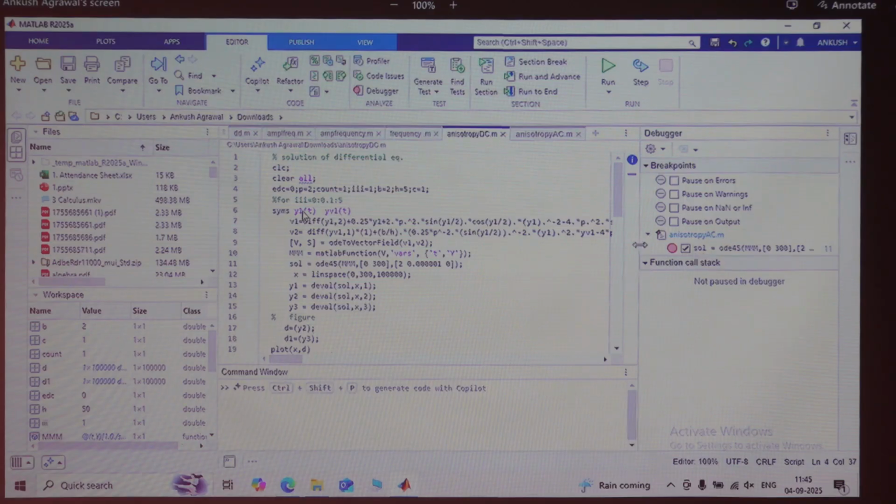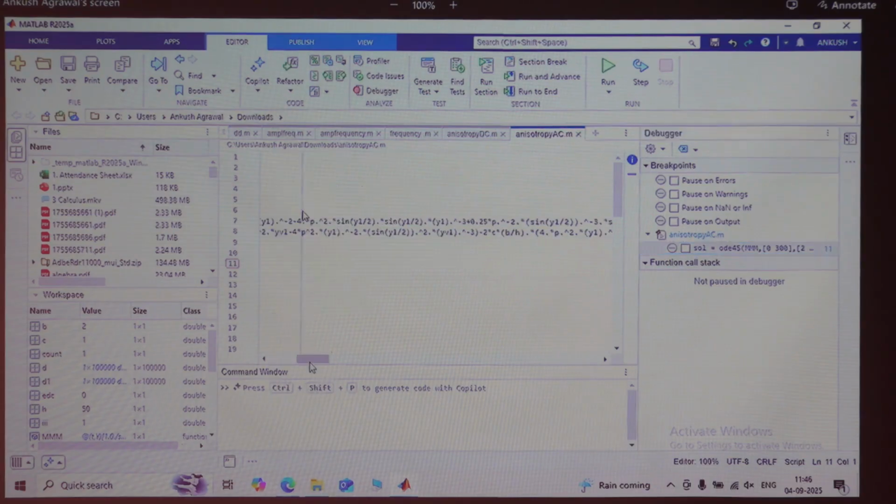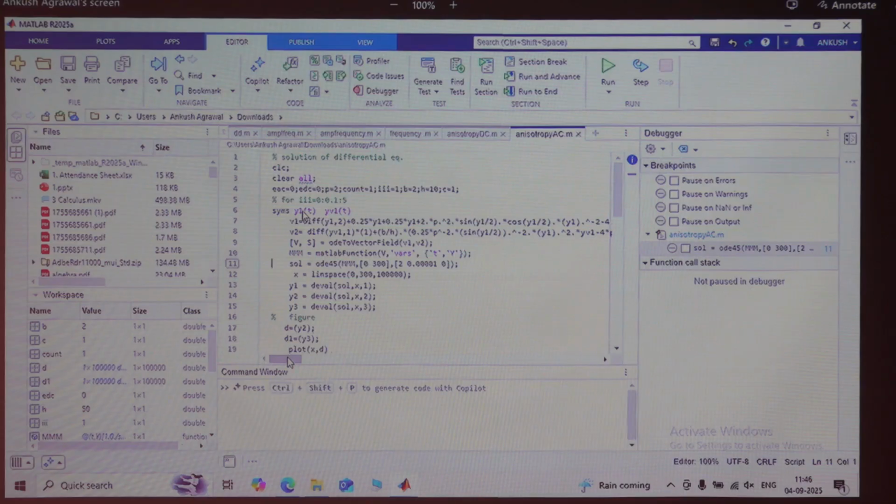Theta, for example, you applied pre-stretch and release. With time it keeps on evolving, then attains the final configuration. Theta is going to be a variable. The other one is lambda viscous. The internal variable, that is the viscous stress developed in the membrane, that is also going to vary with time. We have two variables, theta and lambda viscous here.